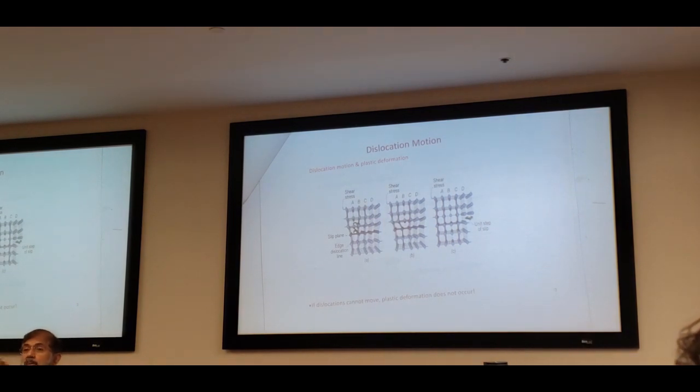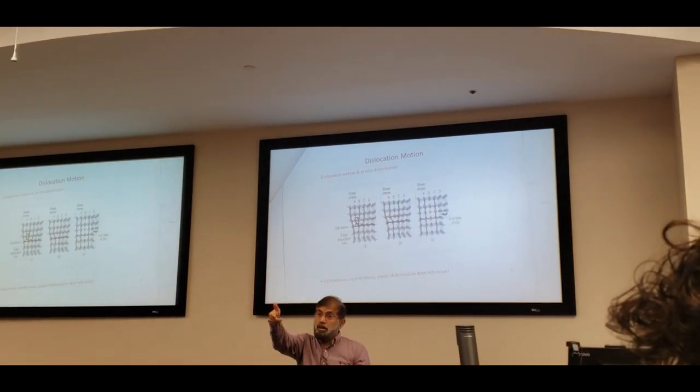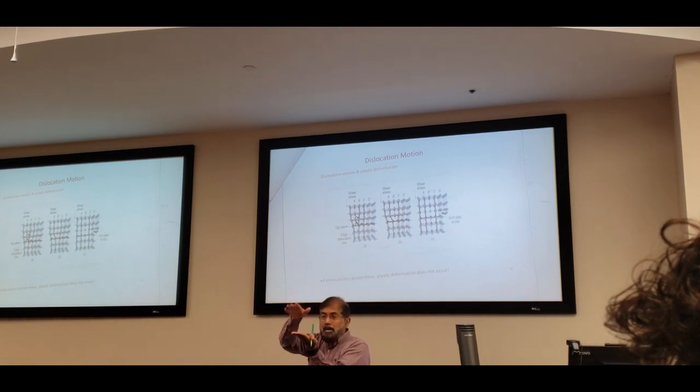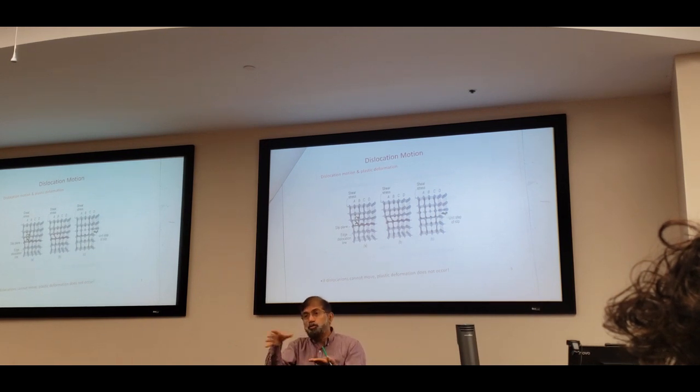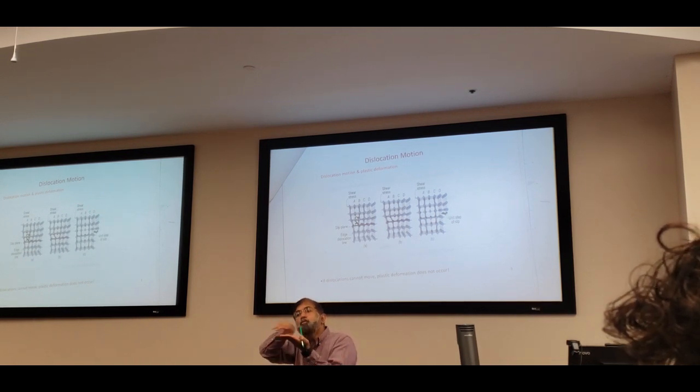Basically, even at room temperature, that thermal energy is there. Because of the temperature, the thermal energy is there. So this can happen very easily. Now, does it happen a lot on a smaller scale? It happens a lot at the microscopic level. In some cases, for example in the silicon industry, the semiconductor industry, whenever you hold a sample with a tweezer, it can exert that force, that shear stress, onto this one, and it can move those planes.